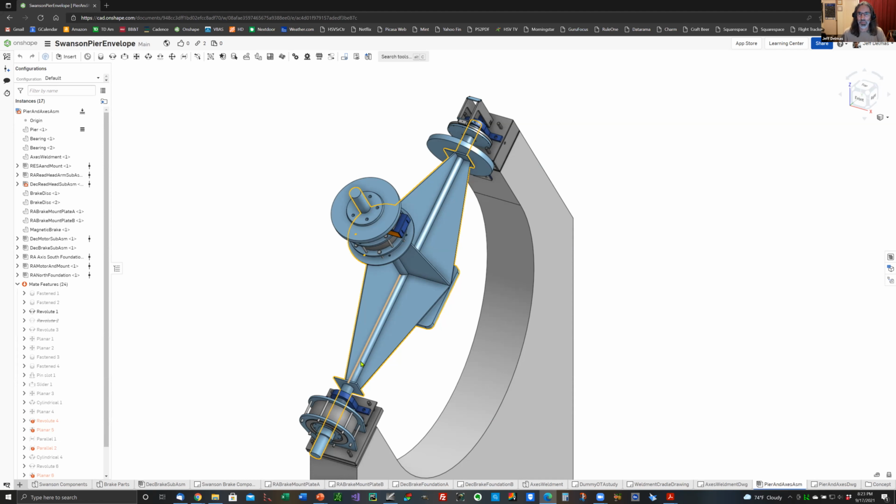Now you can take out a lot of that with software, and we did attempt to, but if your mount's not really good, there's a limit to what software can do. There were times when we actually did use a guide camera. The guide camera would monitor the star, and as the star moved off position, it would send signals to reposition the mount and put that star back in the middle. But that means the star has to move off its position for the computer to recognize it needs to correct for it. So the star dances around and becomes bloated. Instead of a pinpoint, it becomes a circle, and we would see that in our images.